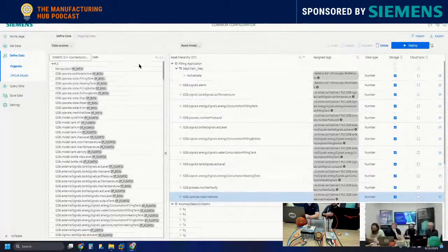So if you have different devices, can you combine data also? Can you rename data so that it all comes in standardized, let's say I have an Allen Bradley machine, and then a Siemens machine and some other vendor. I bring it into my edge device. I can then create a single pipeline that would make sure that everything is standardized.